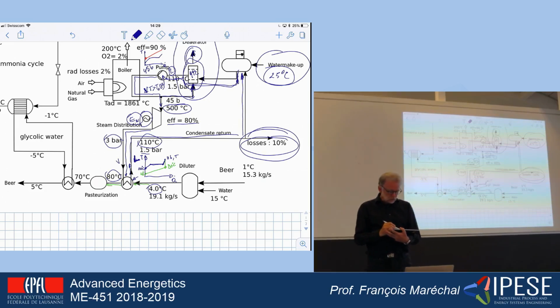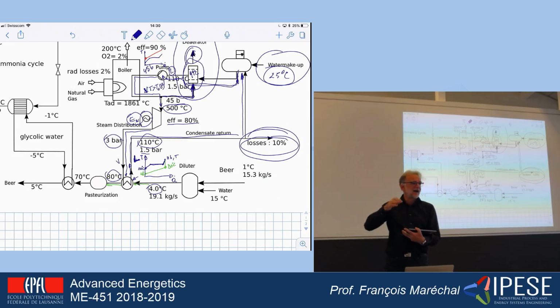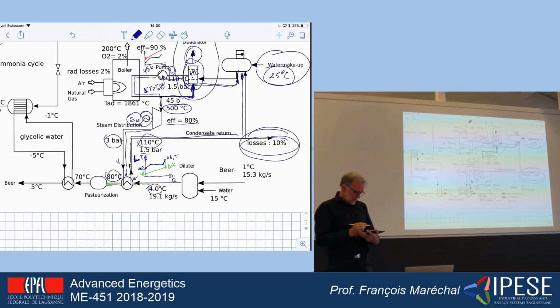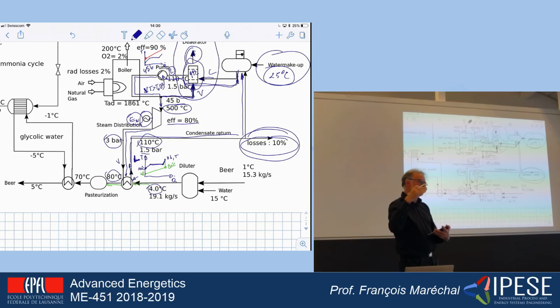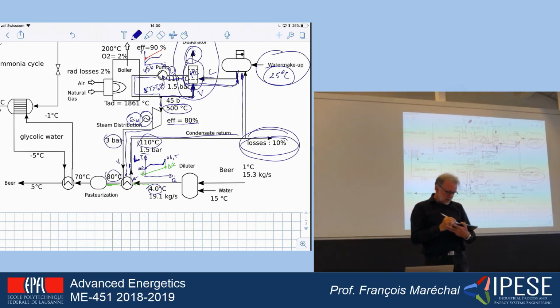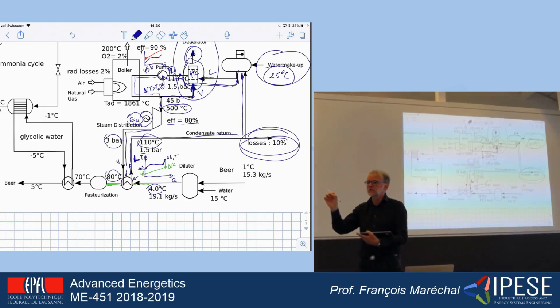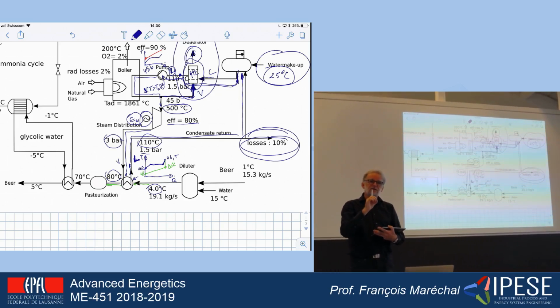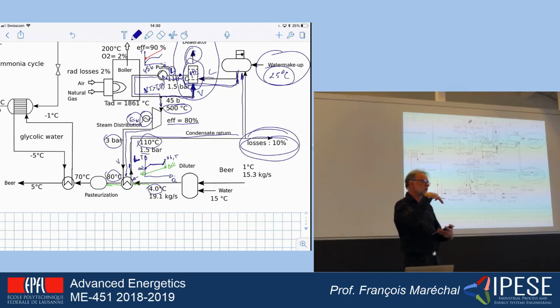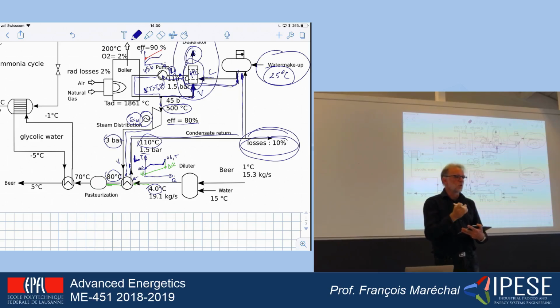Now the deaerator is going to reach a temperature here by injecting a gas which has a high enthalpy, so the vapor, with the liquid which is here. So this is a liquid, this is the vapor phase. And as the vapor phase has a much higher enthalpy than the liquid phase, okay? And if I'm looking at the molecules that are here, you can see that those molecules will be in the liquid phase. So it means that each molecule is going to deliver some enthalpy by condensing. And this heat of condensation will be used in order to heat the liquid water. Okay?